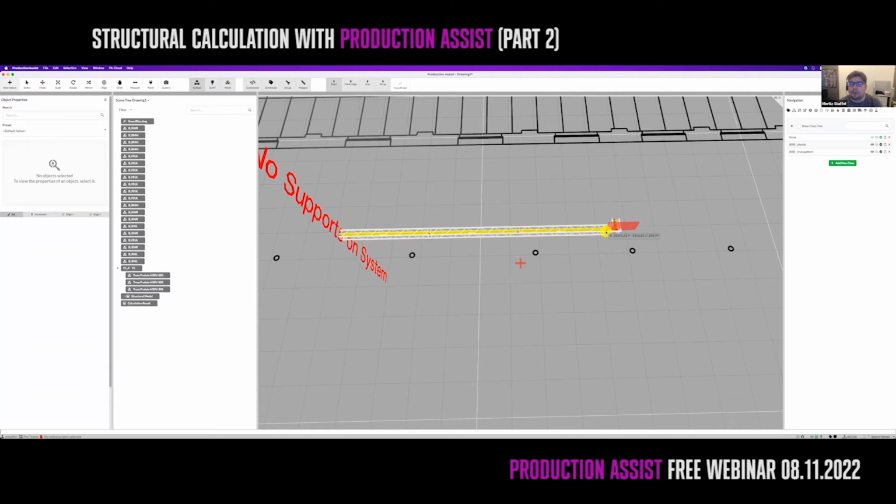So in this case, we want to go in the other direction. For this, I use the Shift key in order to rotate the truss about its rotation point. I can do this multiple times so that it is rightly aligned. Pressing OK will insert this truss. I will do the exact same thing on the other side. Now I have my first part, and it's connected.